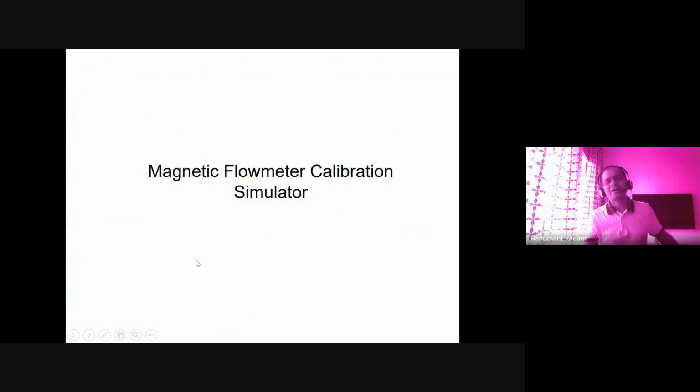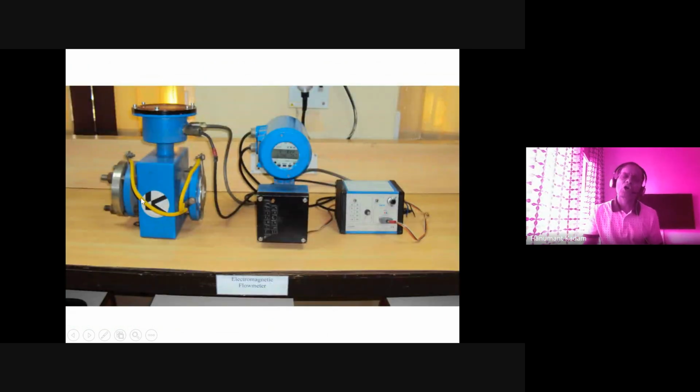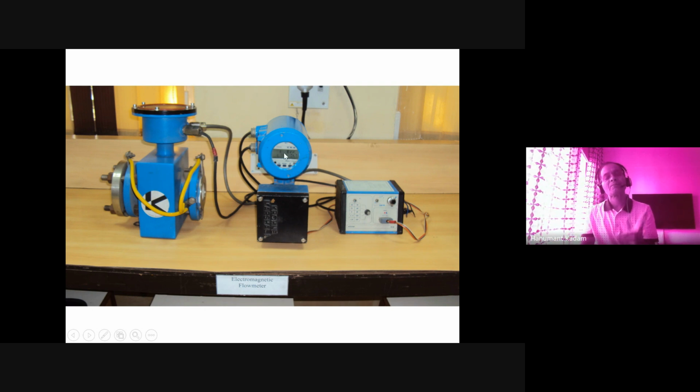But in the lab, whether the sensor is working or not, that you can test. One side you close it and fill it with water, make it a reverse way so that the water will be there, will be steady. Then you can get a reading here. That means your electrodes are working. Or the electronics of this transmitter, transmitter calibration can be done through this simulator.